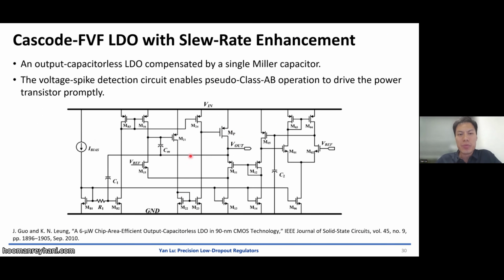And this loop depends on the rate of change, right? The faster the Vout changes, the better the capacitor can couple the variation to the gate of M21. So actually, in the later lecture, I call it a derivative control, right? D control. In the PID control, it's the D control that gives us faster transient response.